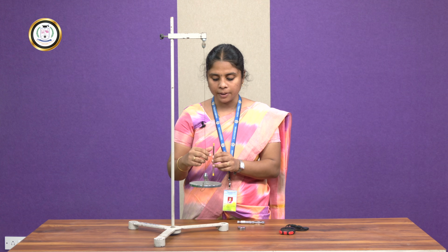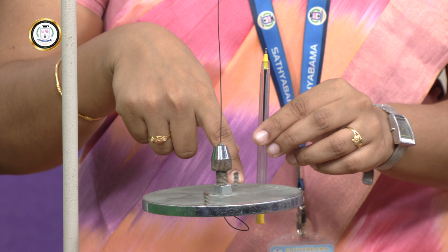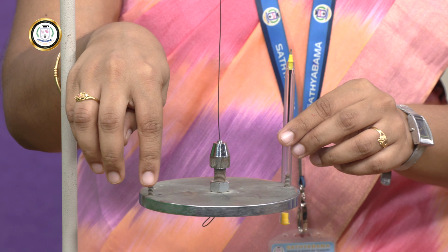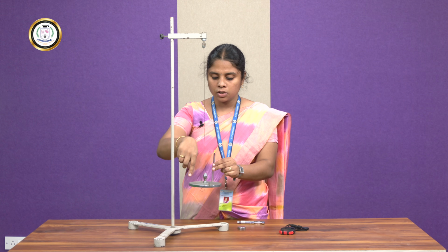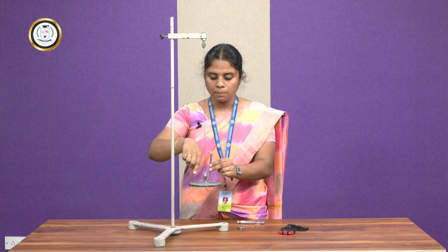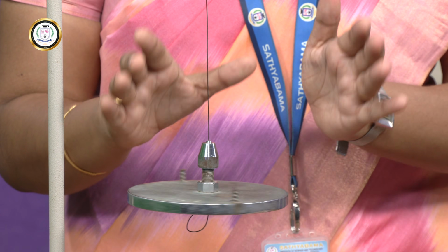To measure a torsional oscillation, let us have a pen. You can see there are two knobs, right? Let us assume this is knob number A. The knob A goes to a new position and comes back to its same original position. See here, this is its initial position A, it goes to the new position and it comes back to its original position A. So, this is one successive torsional oscillation. Like this, you have to measure 10 successive torsional oscillations.